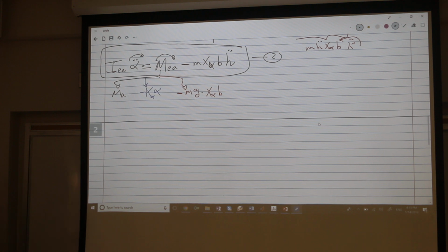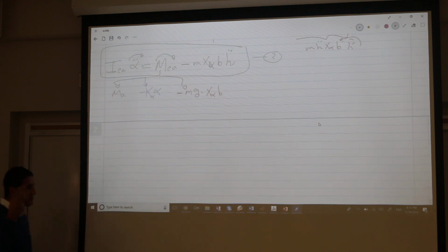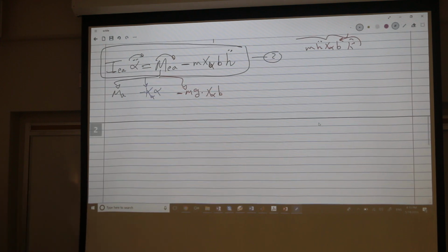The steps that we're doing are exactly the steps that you will be doing in analyzing any dynamical system. If it's an airplane, you will do exactly the same. If it's a submarine, a robot, or a satellite, you will be doing exactly the same. Dynamic model, mass times acceleration equals forces. We've got that. Then we should ensure what? If we want to analyze stability, you cannot say stability and just stop. You have to say stability about what? Equilibrium, or what operating point. So first of all, in order to study the stability about some equilibrium point, you have to ensure equilibrium, which means we have to ensure balance.